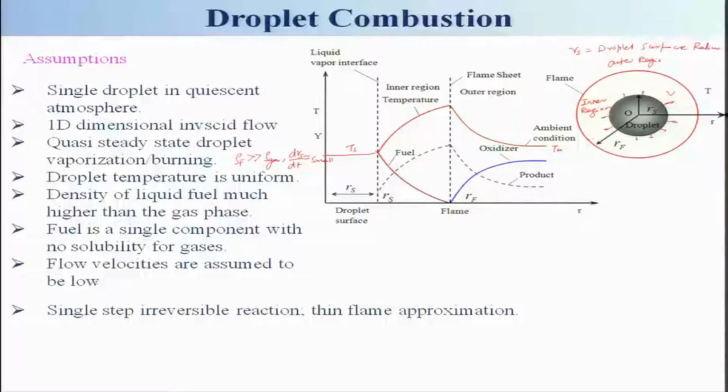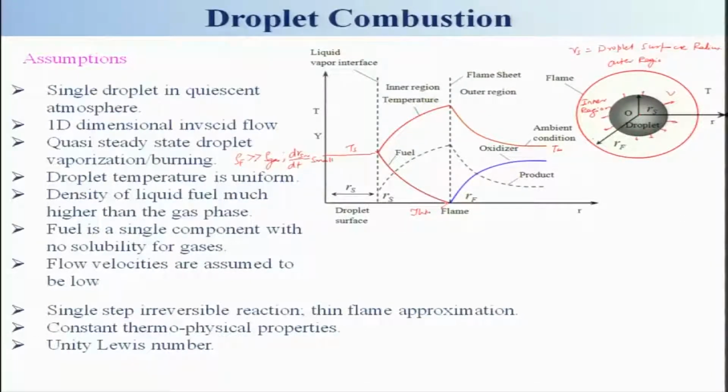And we will be using a single-step irreversible reaction rate, which is, as I have told, the thin flame approximation. We also use constant thermophysical properties as usual, unity Lewis number, and radiation heat transfer is neglected.